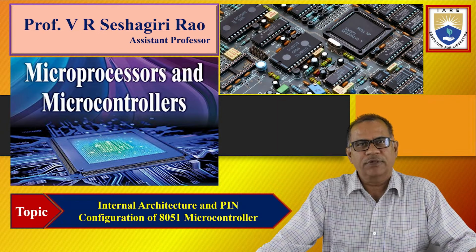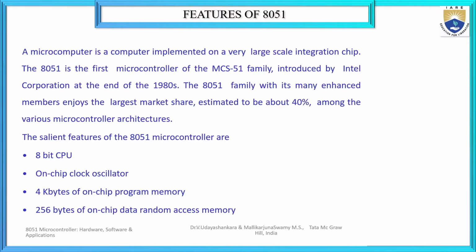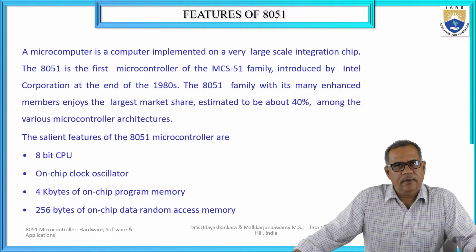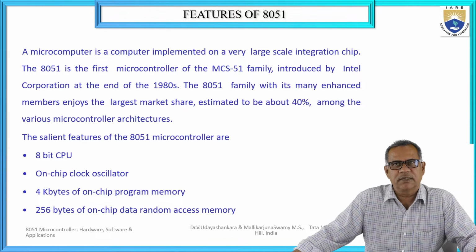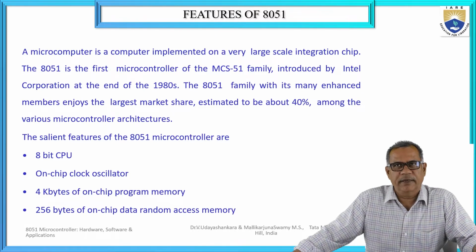Today I am going to discuss the internal architecture and pin configuration of the 8051 microcontroller. A microcontroller is a computer implemented on a single chip. It contains not only the CPU but also internal memory and some other peripherals like ADCs and DACs. The 8051 is the first microcontroller of the MCS51 family, manufactured by Intel Corporation, and it was released into the market at the end of the 1980s.